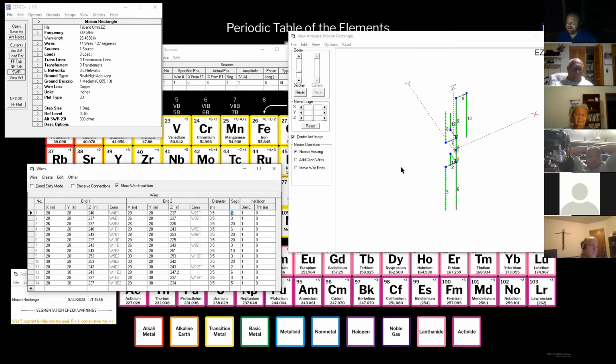But if you go less than about 1 per inch on a VHF antenna, you're going to start to see differences in your calculated SWR and your calculated field strength. So it gives you enough to get by, but without overdoing it in the computer. The reason I ask is because the free version limits you to 20 segments.